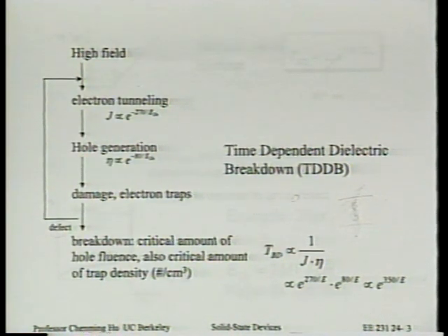There's some condition called ESD, for example. Of course, you can also think about other special applications. But with ESD, the oxide, usually of the input transistor, has its gate connected to one pin in a package. And this pin can be touched by a human finger, which is very unlikely these days because everything is handled by machine.